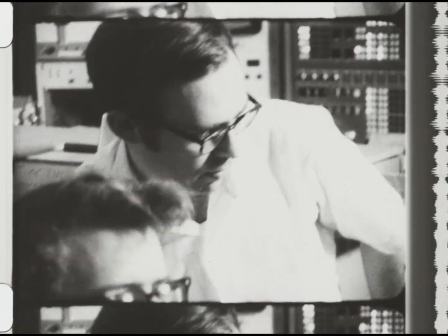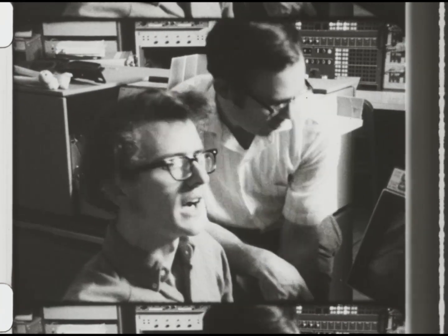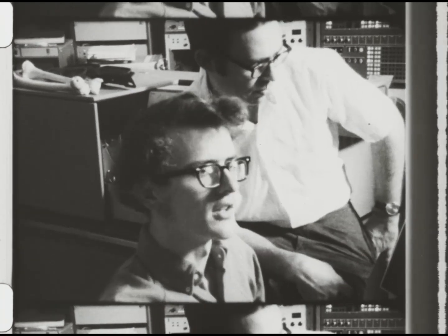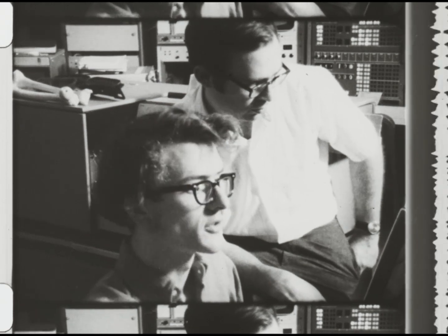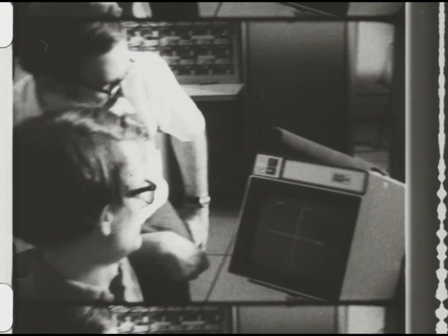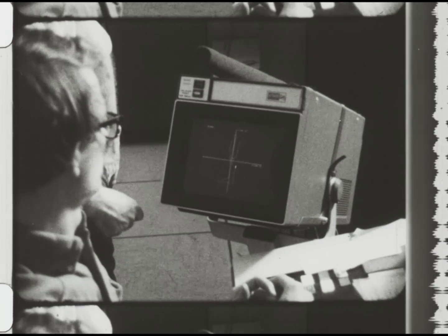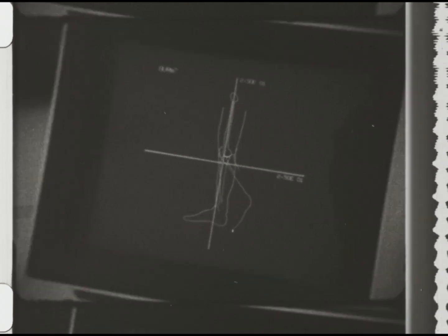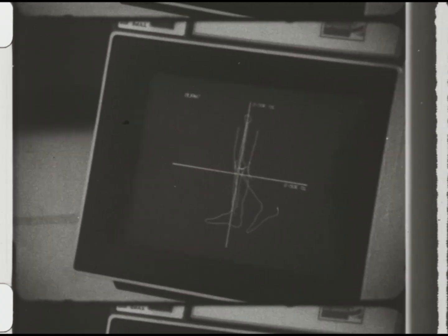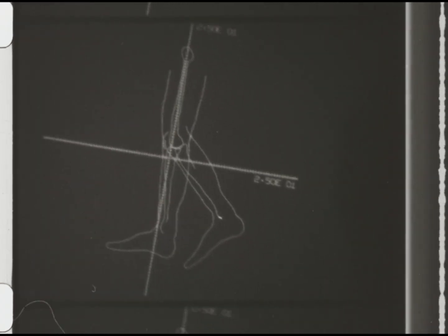First, we'll just show the leg. It is guided by the linkage, but we will study the linkage characteristics a little bit later. But let's just see if the leg is going to move through these positions as we were told before. We've changed scale once again. We're looking at this at a very large scale so that we can see the entire leg moving around, and we'll be able to see whether the linkage does move it through the design positions in the right order.